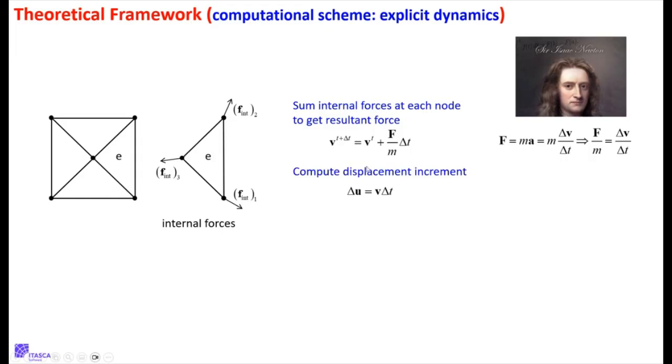And if I know the velocity and I multiply it by the time step, I can get the displacement. This is the displacement, how much it moves. And again, we do the same thing with PFC. Now, if we know the displacements, we have to update these forces. And then we're done. If we can update the forces, we can go back to here and we can just keep doing this every time step. And it's the same thing. We have to choose a time step based on stability considerations, same kind of thinking.